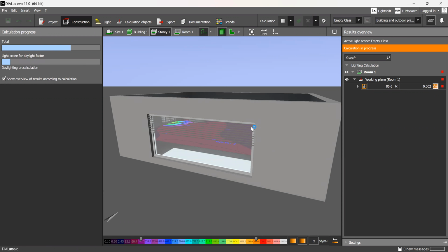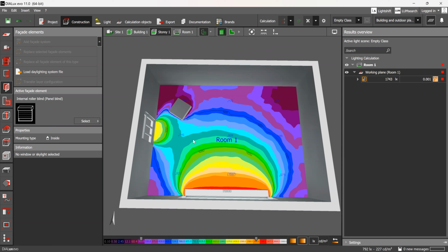Perfect. Now you can see what the room is looking like. Let me describe it on the false color map. The same kind of map is used with, I think in English they call them, fish eye lenses. They are those lenses that make circular photos of the rooms, and then on those they can see how much light is where and whether it's causing glare or not. So referring to your earlier question, depending on one of those cameras, it can show whether there is glare or not in the sun direction.